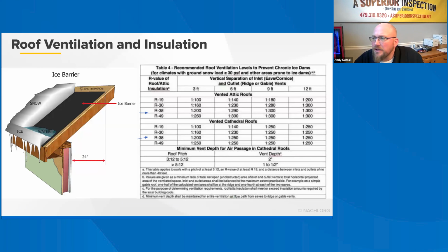All right. So now to ice dams. What causes ice dams? An ice dam is caused by the warming of the attic space, obviously when there's snow or ice on the roof. And while the attic ventilation and the insulation contribute to prevention of ice dams by keeping attics cold, they can be overpowered by other attic warming effects, such as air leakage from the house into the attic through ceiling bypasses, chases, open gaps, uninsulated ducts placed in the attic.